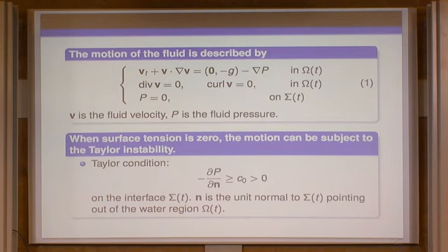If it's decreasing, the force just rips open the fluid, and an air bubble could form, and then this formulation would be wrong. In this formulation, we assume that initially the fluid domain is bounded only by the free surface, and if suddenly an extra surface boundary appears in the interior, that is a topology change, and this formulation has to be reformulated. Or you can say the situation is unstable, so you cannot solve it if the problem is violated in this way.